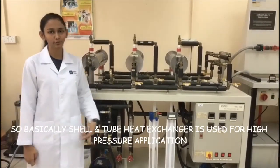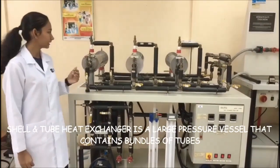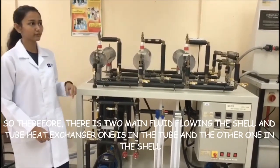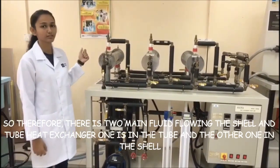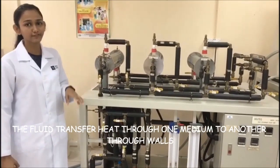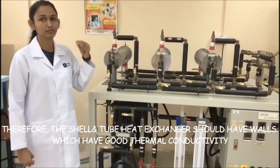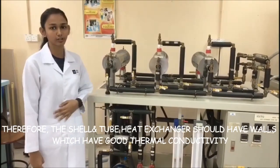So basically, the shell and tube heat exchanger is used for high pressure applications. It is a large pressure vessel that contains bundles of tubes. Therefore, there are two main fluids flowing in the shell and tube heat exchanger: one in the tube and the other in the shell. The fluid transfers heat from one medium to another through the walls. Therefore, the shell and tube heat exchanger should have walls with good thermal conductivity.